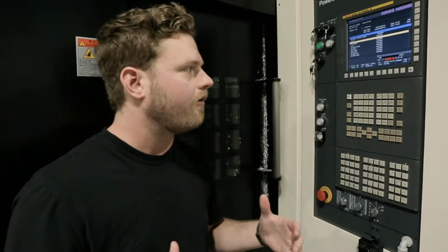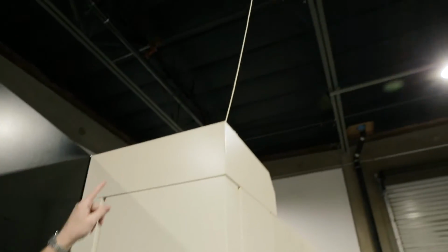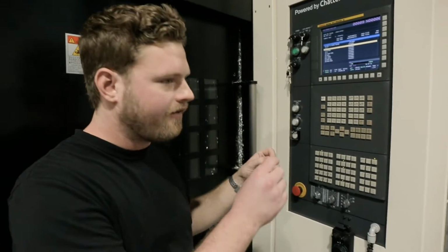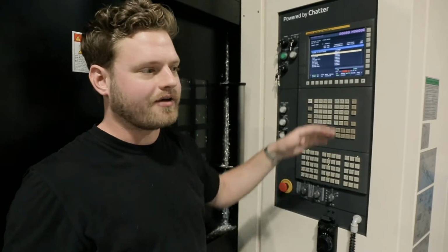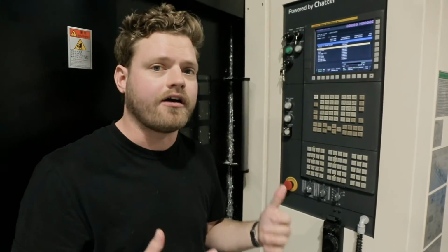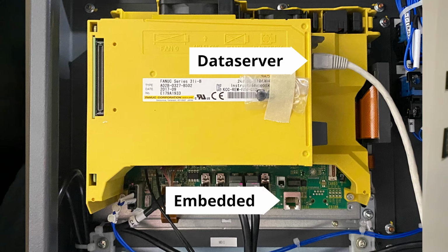Another thing that's worth talking about is network testing. On this control here, we have the Ethernet cable, which is just dropped down from the top, routed straight into the back of the control. On some machines, they actually have a facade, like a wire on the outside that you can plug into. It's really important with those wires to make sure they're plugged into the correct interface internally. Typically, if you have that wire on the back, the machine tool builder has routed that somewhere on the machine, and you want to pop open the back of the interface and see which of the two Ethernet cables you're plugged into. We'll throw up a graphic right here.